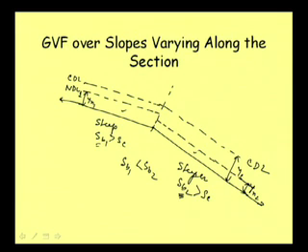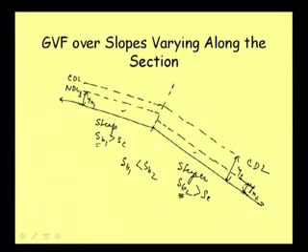As we know, the disturbance at upstream will be controlling the supercritical flow. So, we can take that this is a section where some disturbance will be occurring, but this being supercritical flow, it will not be affected by this disturbance.